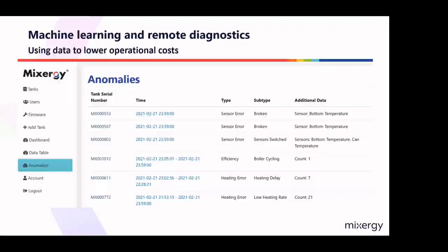So I want to talk a little bit more about what else machine learning can do. With machine learning we can see things like if suddenly there's a high heat up period or a quick rapid depletion of hot water, it could be that there's an external leak. If it's above a head, you'll notice it. If it's under a concrete floor or in a plant room, the cylinder is able to use machine learning to monitor its surroundings to say, we think there's a water leak, and notify the asset manager. In the local authority world, it's able to do welfare checks with machine learning.